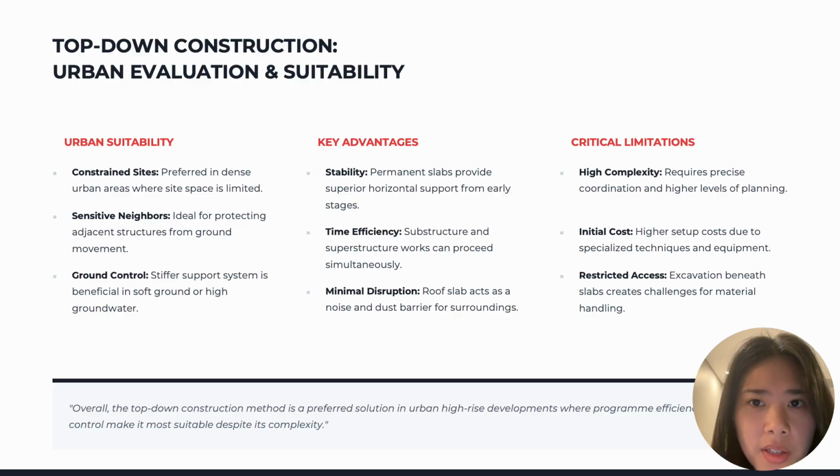The top-down method provides better control of ground movement. It is suitable for dense urban areas with limited space. It also improves project efficiency because construction can occur simultaneously. However, it is more complex and has higher initial cost.